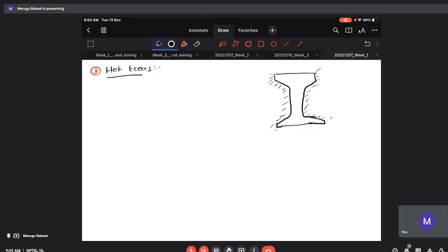Now when this is getting solidified, at this portion you see some type of stresses, because this tries to pull the entire thing this side and this tries to pull the entire thing the other way. You understand? During cooling, the shrinkage happens from liquid to solid. When this happens, we get residual stresses inside this component, which result in crack formation here or here, anywhere.